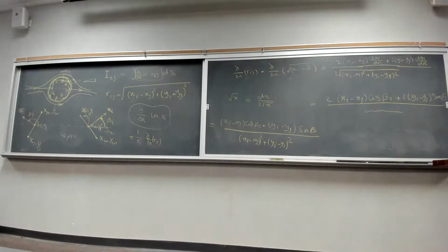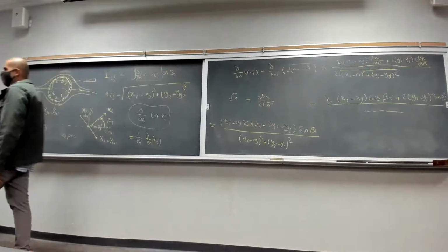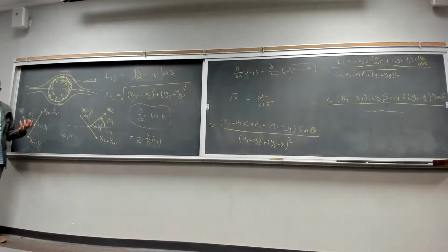I guess let's just stop here and finish this example in the next lecture. But eventually, what we are going to do is find an equation that gives us I of ij, and then using that, we are going to find the velocity potential as a function of lambda induced on each panel. I of 1,2 will be one number, I of 1,3 another number, I of 1,4, I of 1,5, I of 1,6, all of those different numbers.